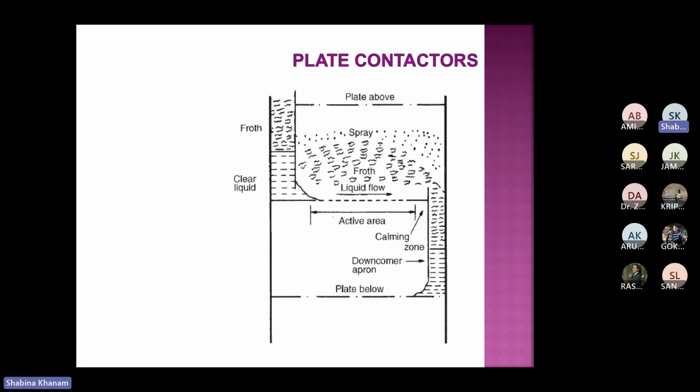So when we consider this, this is a single plate, and if you consider this particular section, this is nothing but the weir height, right? That we have discussed. And this zone we call the downcomer apron. This zone is called the downcomer, and this vertical line you can see is nothing but the downcomer apron. And we have already discussed the active area in the AICHE method before.